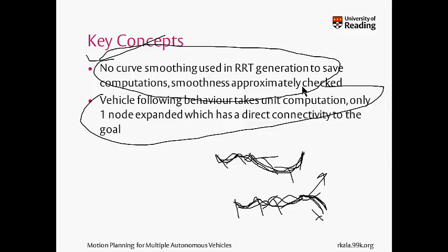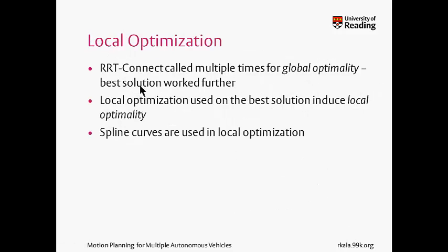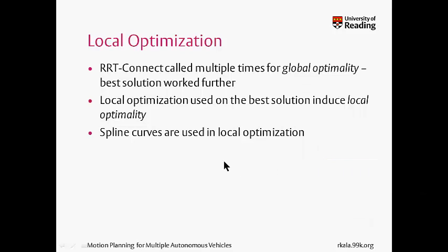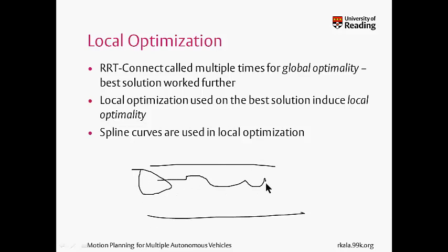And as I mentioned, for the most basic behavior, I take a unit time step. So by these two slides, it is clear that I need to explain nothing more in the use of RRT-Connect for solving the problem. The same RRT-Connect methodology would be used, and like RRT could solve scenarios like this by some kind of expansion from the source to the goal out here, RRT-Connect will be able to do that in a very similar manner.